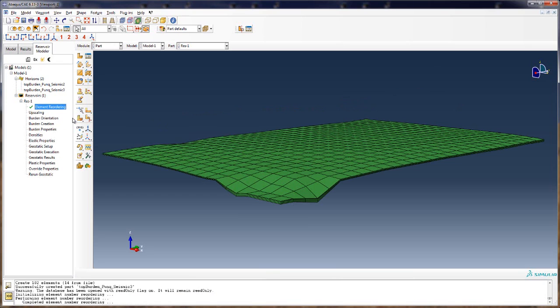What that does is it changes the element number in such a way that later on when we merge, let's say, 2 layers, the layer with the larger volume of fluid will retain that element number, and basically we'll retain some of its properties like the amount of fluid and things like that.